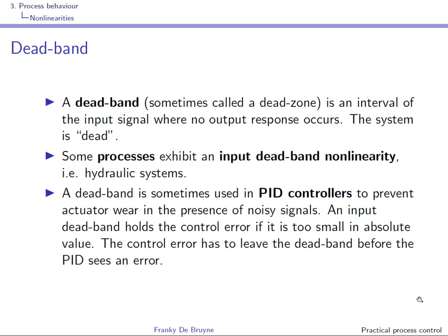An example is the hydraulic system that we've seen just before. A deadband is sometimes used in PID controllers, and the idea is that it will allow to prevent actuator wear in the presence of noisy signals.